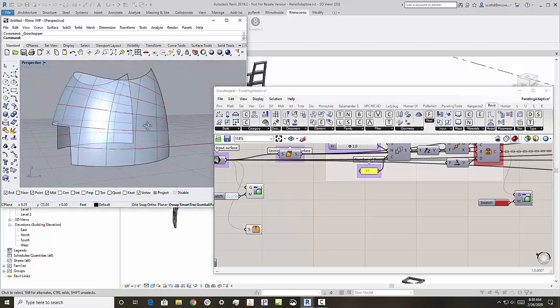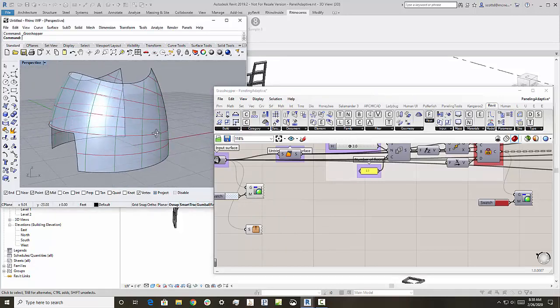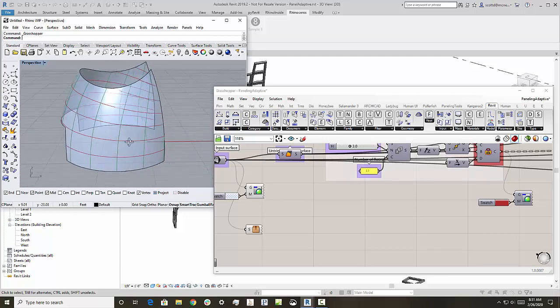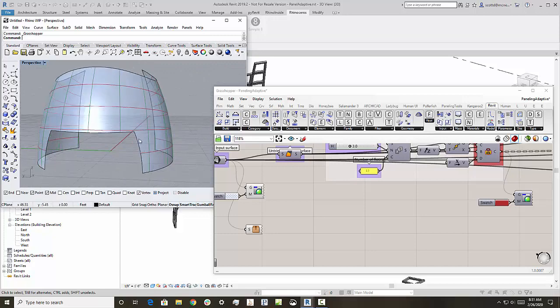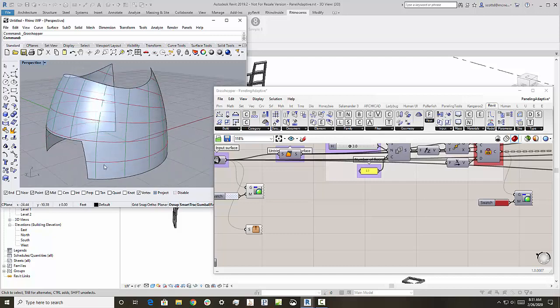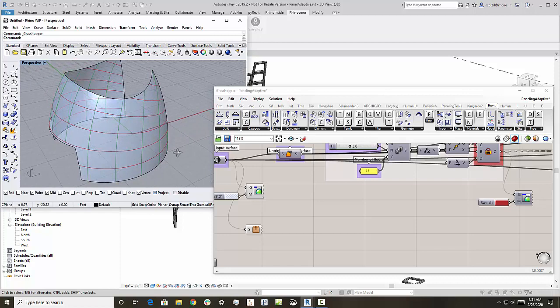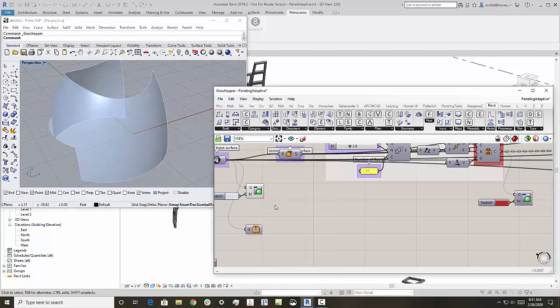One of the things I want to be clear about on this is that this is just a surface whose isoparms go in an odd direction. It's trimmed. Nothing's really that straight. In this case on purpose, of course, but it's a fairly complex shape. And so one of the things that's nice about this is you don't have to worry about having exactly the right surface to panel, because we're going to use Grasshopper and a plugin for Grasshopper called Paneling Tools to now split this up. So I'm going to turn off some of these lines a little bit.